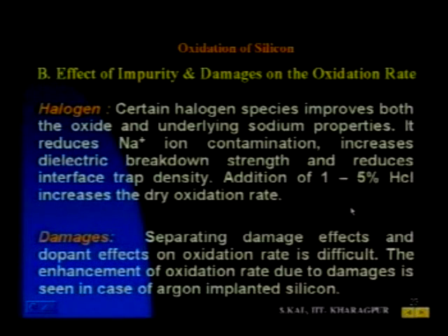Because of implantation, if it is a high energy implantation, the crystal is going to be damaged a little bit, and this damage enhances the oxidation growth rate, because if the silicon crystal is damaged, the bond structure weakens, whether in oxide or in silicon.